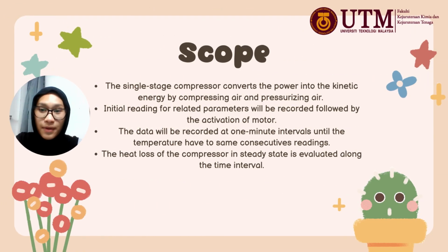So for the scope, the first one is that the single stage compressor converts power into kinetic energy by compressing and pressurizing air. The second one, initial readings for related parameters will be recorded, followed by the activation of the motor. The third one, the data will be recorded at 1 minute intervals until the temperature has the same consecutive readings. The last one, the heat loss of the compressor in steady state is evaluated along the time interval.